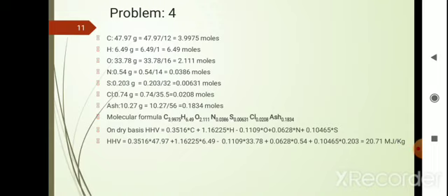So drying is an important pre-treatment in many biomass energy conversion processes, especially gasification, incineration, pyrolysis, etc. If you have properly dried the biomass, the heating value will be increased. So that is the conclusion from this problem.